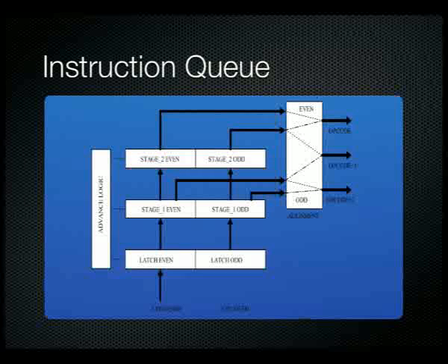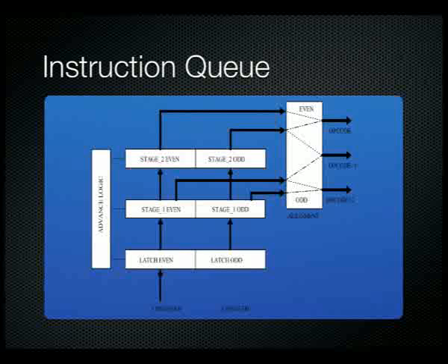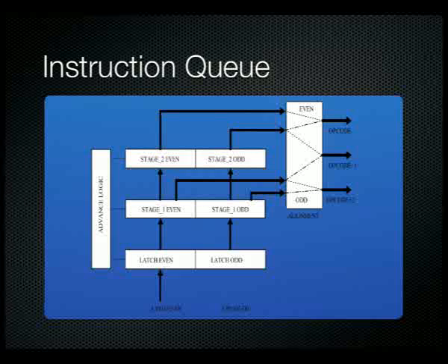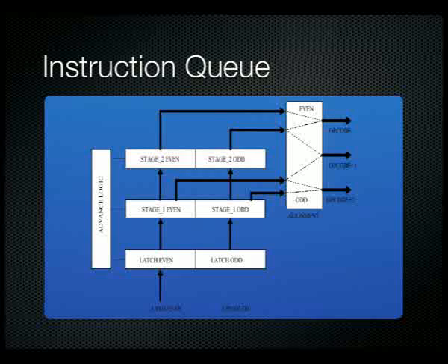This speeds up our processor a little bit, because we don't have to wait to fetch that instruction and the operands. They're already sitting inside our instruction queue, inside the processor, ready to be read very quickly when we get around to executing them. When it comes to this instruction queue, we effectively have three buffers. We have a latch, which is simply a buffer for holding the next instruction in case we haven't advanced the queue but we've asked for a piece of data. We'll stick it inside the latch and wait for the queue to advance.